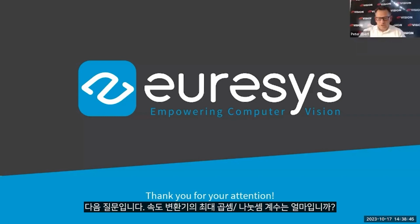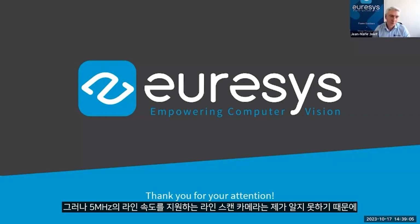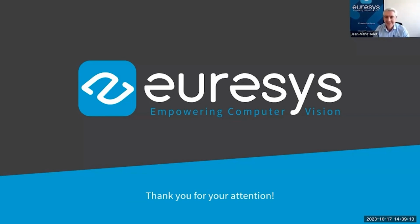Next question. What is the maximum multiplication or division factor of the rate converter? So the maximum division is by 1000, and the maximum multiplication is by 1000. There is a limit, of course. The multiplication cannot give a rate higher than 5 megahertz. But to be honest, I don't know any line scan camera that supports a line rate of 5 megahertz. So we have, I think, a comfortable margin regarding this.